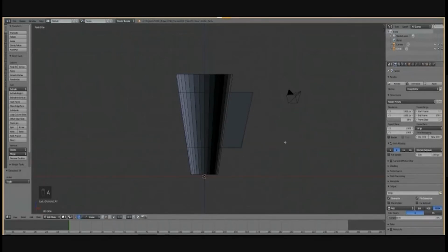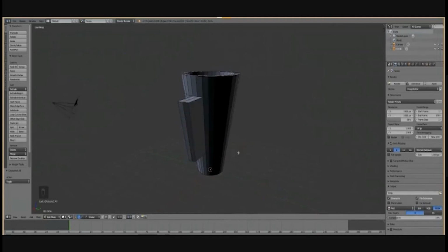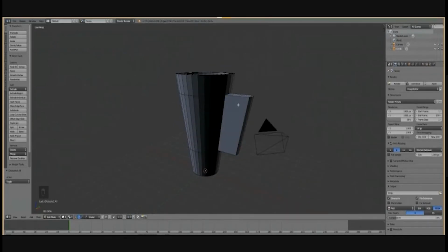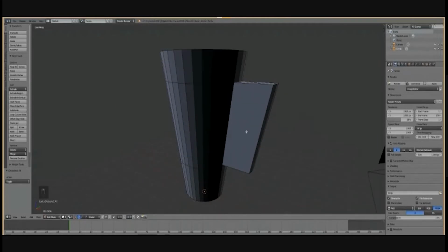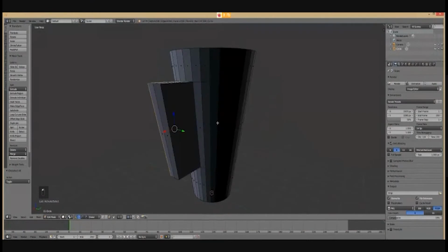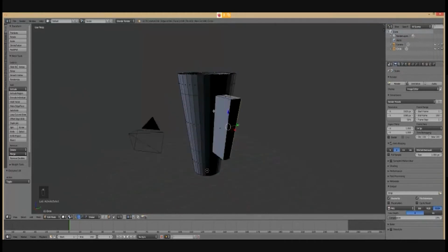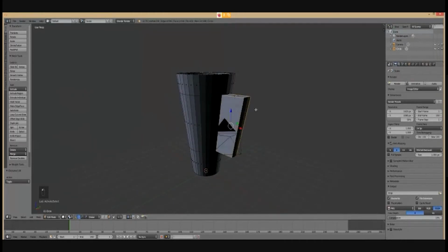Okay, cool. Obviously, this is not a handle because you can't put your fingers anywhere, right? So we need a big hole over here for you to grab the coffee cup. And the way that I'm going to do it is I'll go back to faces, right? So I can select different faces. I'll select one face over here, and while holding shift, I'll select this face over here.